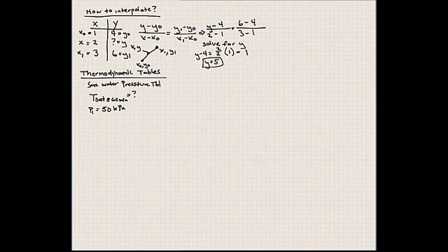So at 50 kilopascals, we know that the saturation temperature is 81.32 degrees Celsius. The table also provides us that at 75 kilopascals, our saturation temperature is 91.76 degrees C. What we are interested in finding is this T saturation at a pressure of 60 kilopascals.